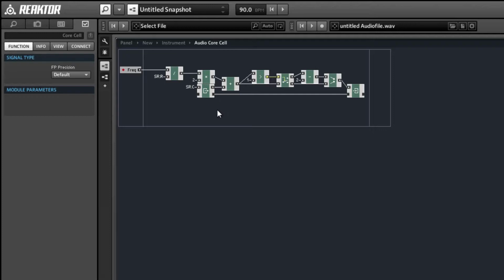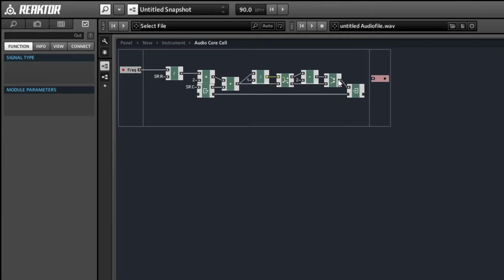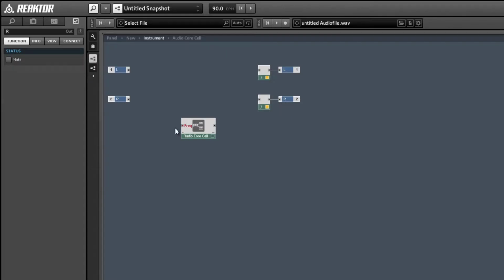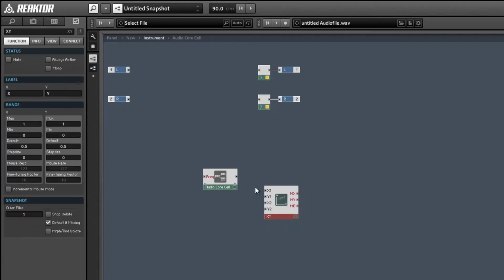So every time we want to complete one full oscillation, we need our phase accumulator to rise by a total value of 2. And the phase accumulator will, as we've programmed already, keep that value within a range from -1 to 1. Every time we get over 1 and cycle back around, we've begun a new oscillation for our oscillator. And a phase accumulator itself is basically a ramp oscillator.